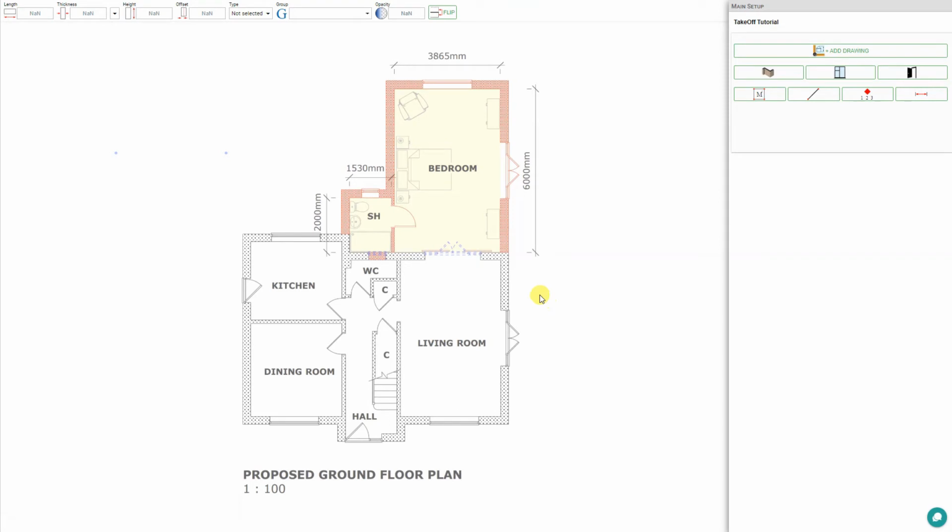And we've covered enough of the basics that we can actually start drawing some walls on our floor plan now. So to start with, let's select the wall tool. And because we have a complex wall here to draw, we will leave this set at multi-wall, and the length will be automatically calculated for us. As an exterior wall, the thickness is 300 millimeters. This item here will allow us to adjust the shape of our wall, and we'll come back to this in a few moments. We'll just leave this set at rectangle for now.